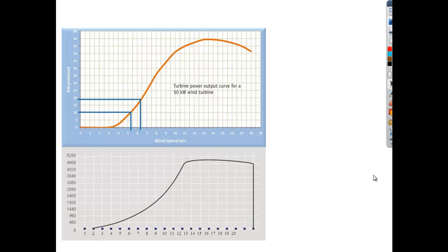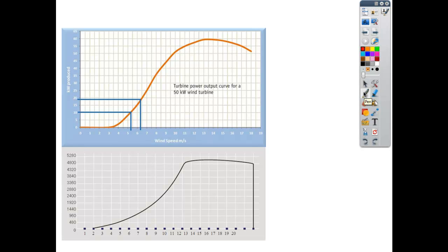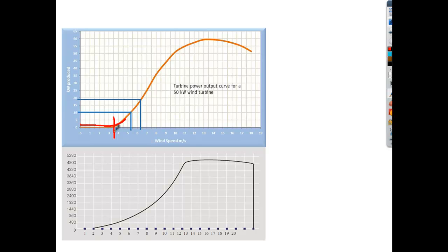And here's something very few people know about wind turbines. You usually think that as you increase the wind speed, a wind turbine produces more electricity, but that is not true. If you notice here in meters per second, when you're under possibly 7 or 11 miles per hour of wind, you don't make any electricity. It's just not strong enough. So you have to have a strong wind at a consistent rate, and as the wind gets stronger and stronger, the production of electricity goes up and up until you reach a peak.